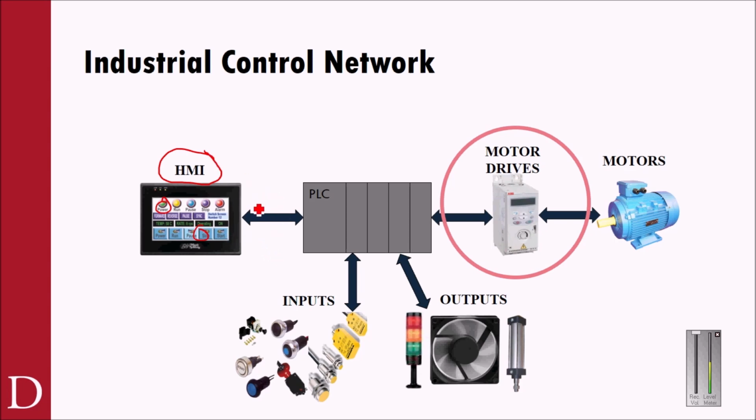Well, the HMI sends its signals over to the PLC. The PLC then is really the traffic cop. He's the decision maker. In addition to getting inputs and sending data to the HMI, the PLC is also getting inputs and outputs to real world devices. Switches and sensors, push buttons, light trees, and output field devices such as motors and fans and pneumatic solenoids and things like that. All of that's happening.